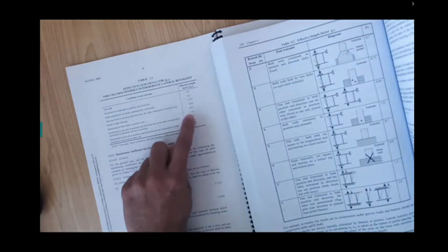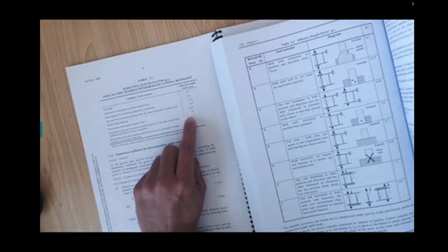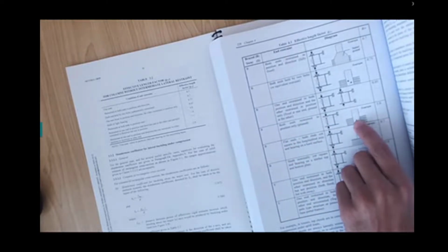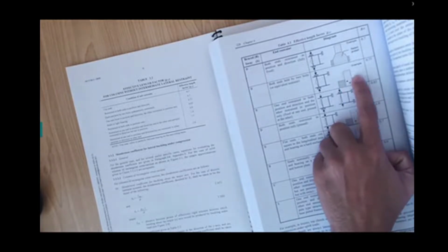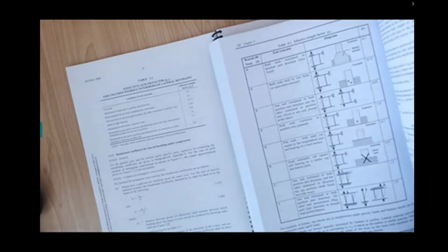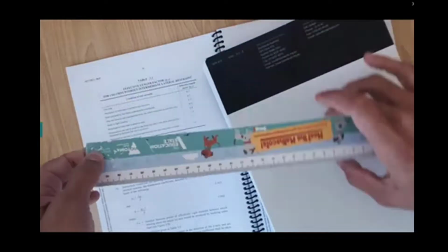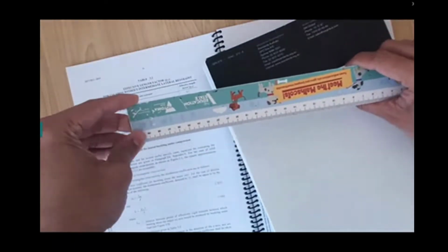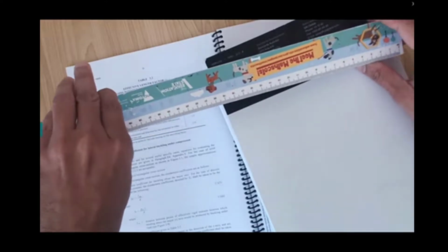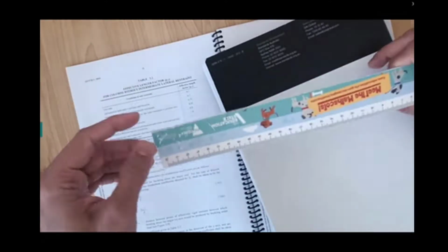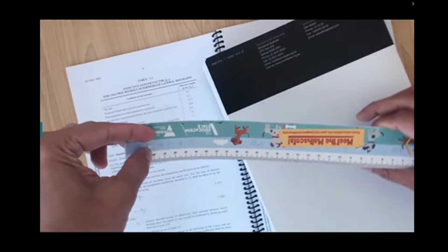Now this is good. This is getting worse. Okay, 1 and 1.5. Restrained at both ends in position only. So a pin is 1. If you have a pin, like you have one bolt only, and you put one bolt like this, you can rotate easily, right? But if I put two bolts, it is not easy to move. One bolt is kind of a pin, you can see. If I put two bolts like this, it is difficult to rotate. It still rotates, but it's difficult.